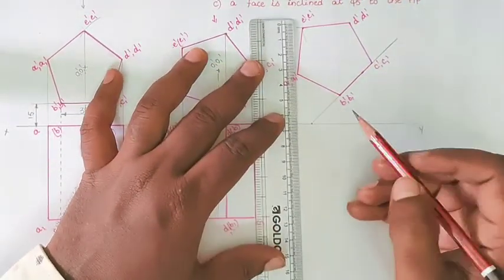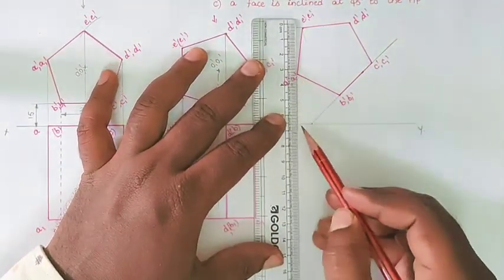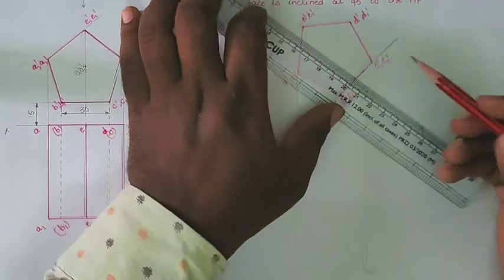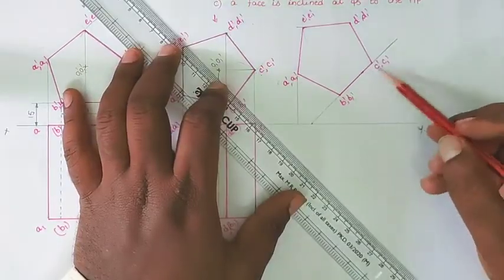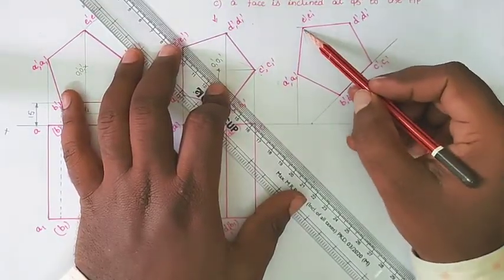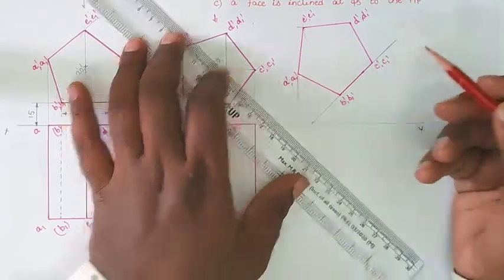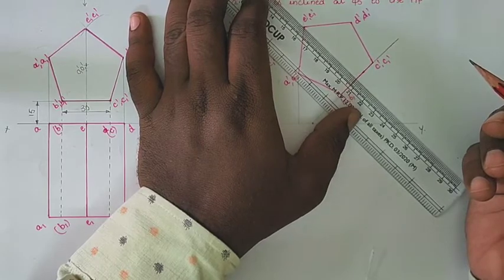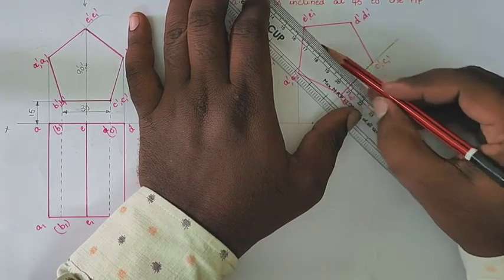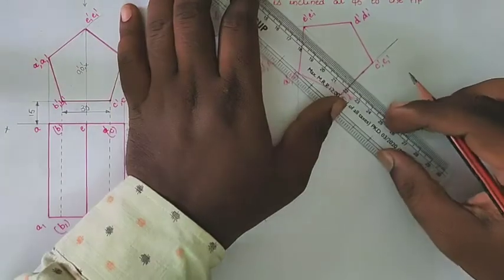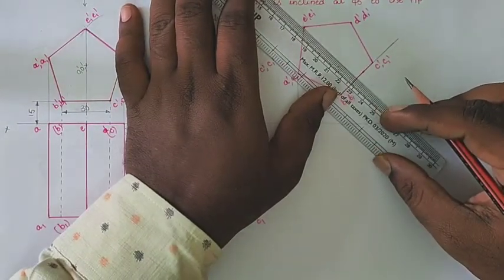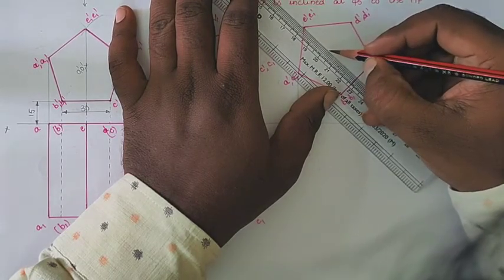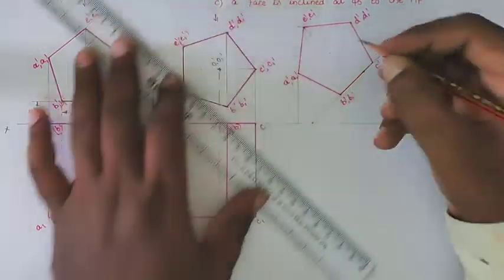Now from the front view we will draw the vertical projection lines. So here also you can locate the center point of the front view. So after that we will draw. So here the fixed corner is this one. So from this one we will locate the midpoint of this line. So you can measure the line length of this one, 48. So here we get the center point.